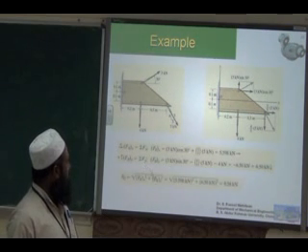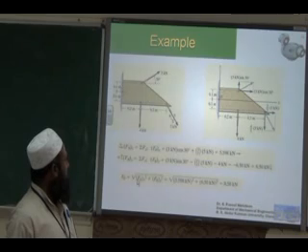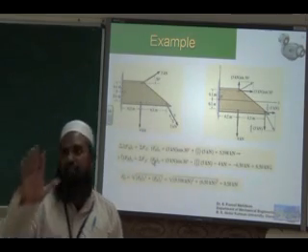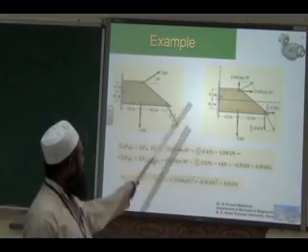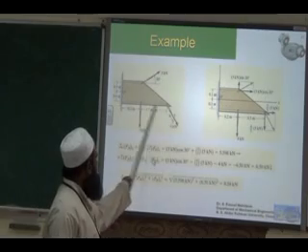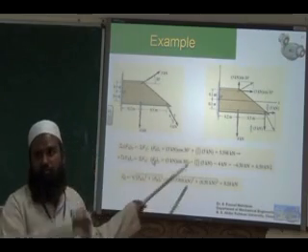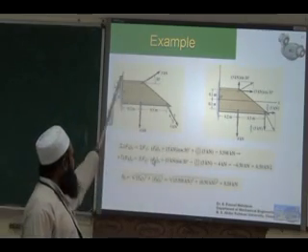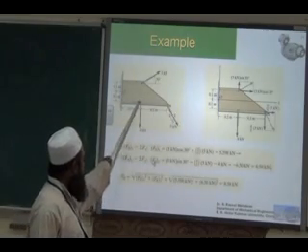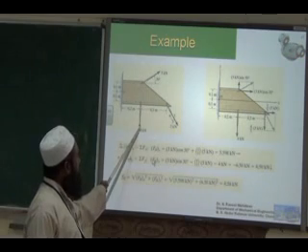Then we have to find out the value of the resultant force, using the Pythagoras theorem. It is a coplanar system; the forces exist in a single plane. So first we resolve the inclined forces. Two inclined forces we have. This is a vertical force, parallel to the y direction. So x is the horizontal direction, y is the vertical direction. It is negative y, downwards.